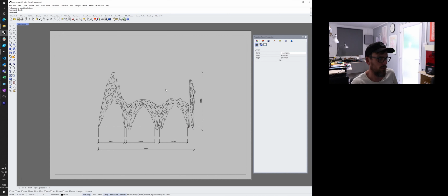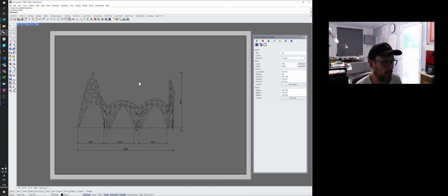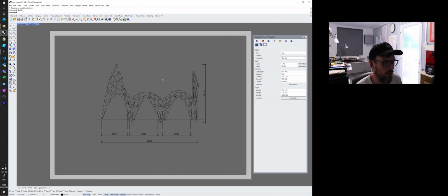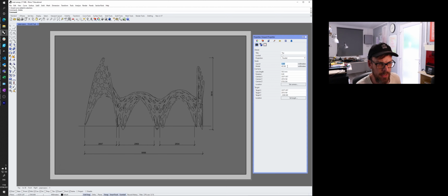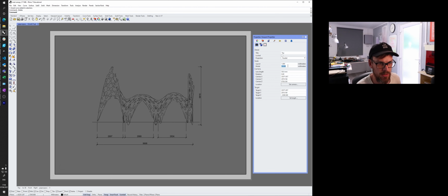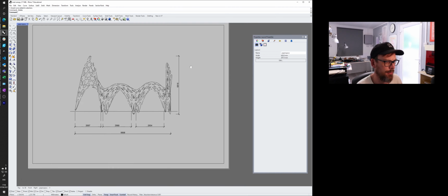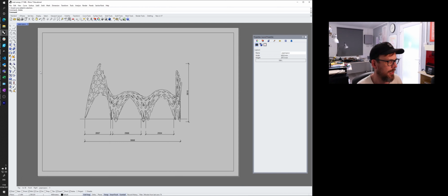Okay, so we've now got our drawing in here. We can double click and we can move around, scale. As you can see, I've got my viewport properties open, which is under standard, the kind of rainbow donut shape. And I can now click on there with me in the edit mode. I can set layout 1, 2 and choose an appropriate scale. So 1 to 50 looks good. I'll double click out of that, so I'm moving the whole sheet around, and I can go to create a